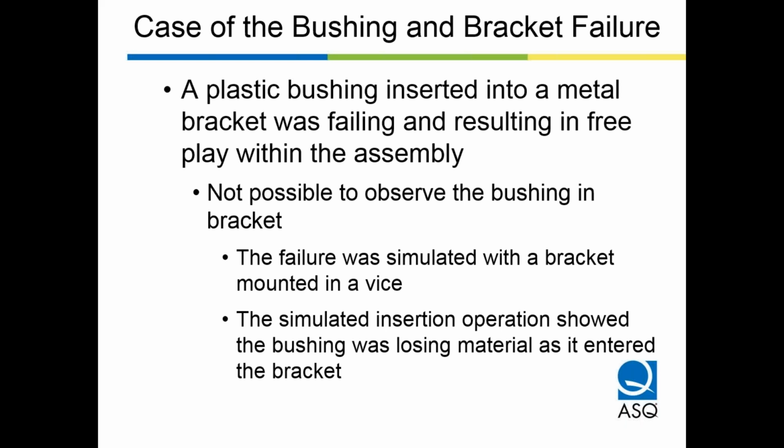So I wanted to evaluate this empirically. This was not a definitive test, it was an exploratory test. I hooked up failed units to an oscilloscope and they do not generate a signal when moved. New units out of the warehouse did, so I took a new unit and smashed it with a hammer. And it still generated a signal. That dent was much more severe than the small one from the screw, so I had an awkward situation when the production manager walked in and caught me doing that. It's okay, I'm doing science. He gave me a weird look and ran away, but I discovered my hypothesis was wrong.